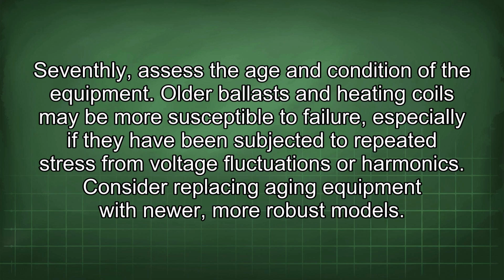Seventhly, assess the age and condition of the equipment. Older ballasts and heating coils may be more susceptible to failure, especially if they have been subjected to repeated stress from voltage fluctuations or harmonics. Consider replacing aging equipment with newer, more robust models.